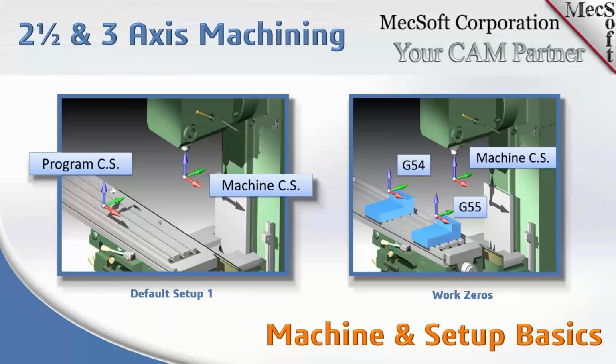That setup, the orientation, meaning the X, Y, and Z axes, by default are aligned with your world origin in the CAD system. So by default, the X is to the right, the Y is looking into the machine, and the Z obviously is pointing up to the machine spindle.